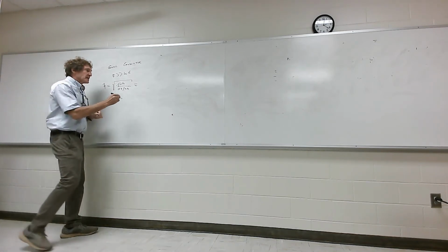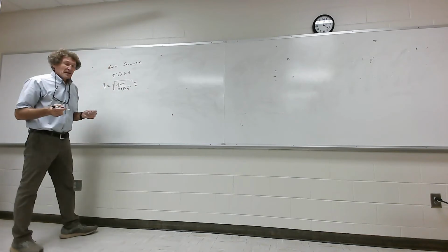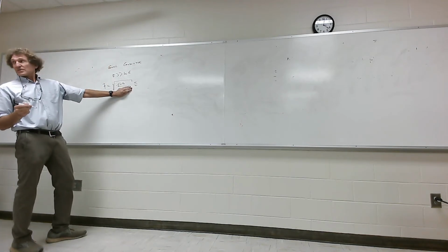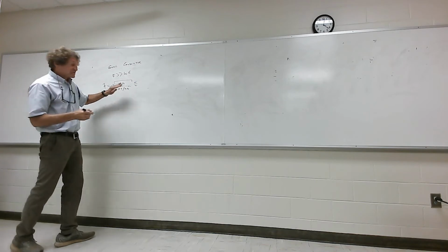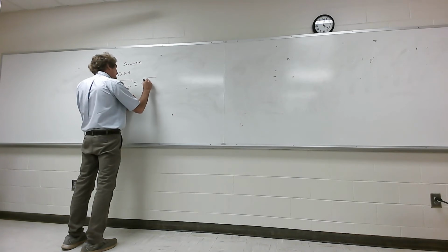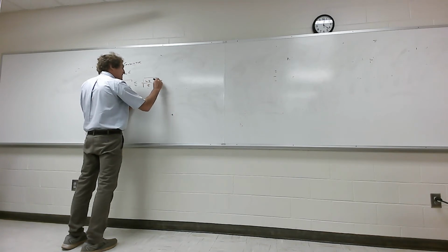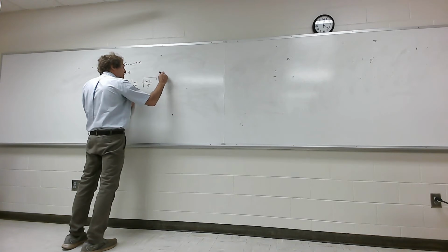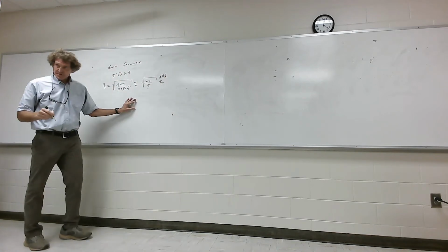What does this approximate as, class? Just get rid of the j omega epsilon, right? And this becomes simply the square root of omega mu over sigma, and it would be e to the j pi over 4 radians or 45 degrees. Do you all agree with that?